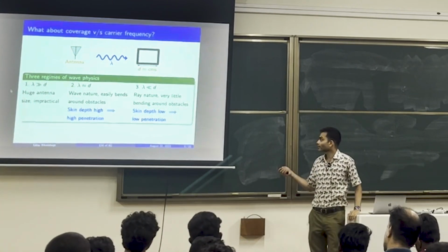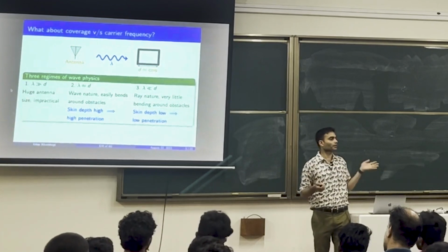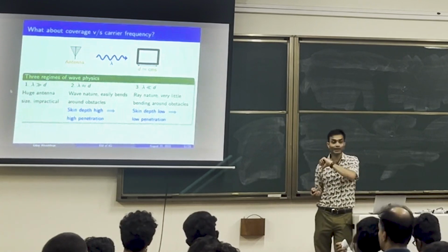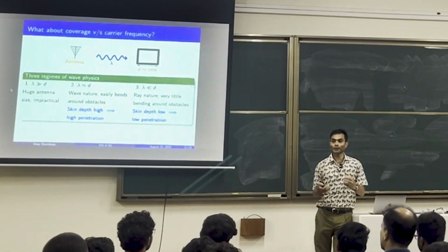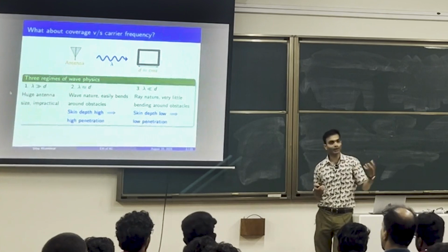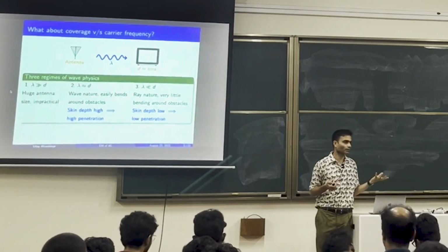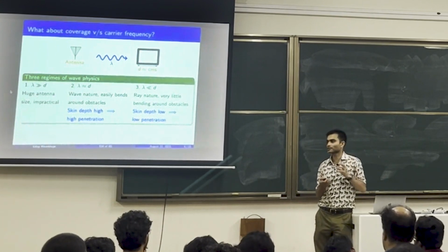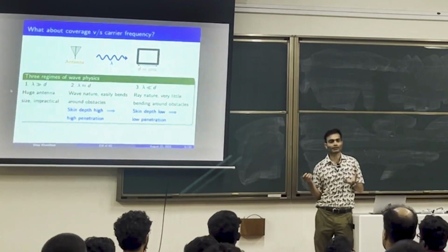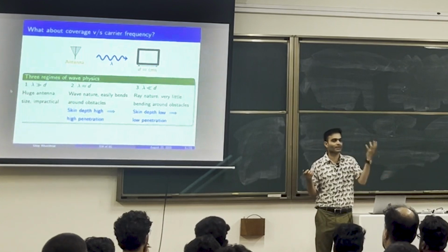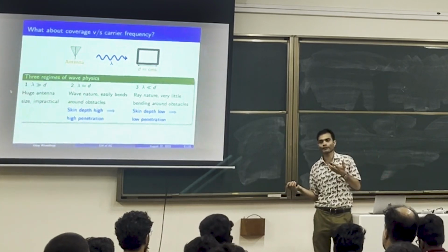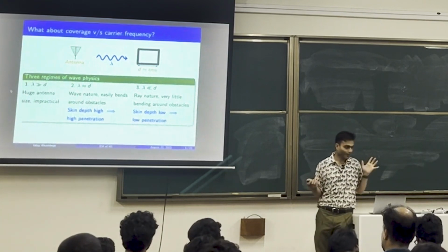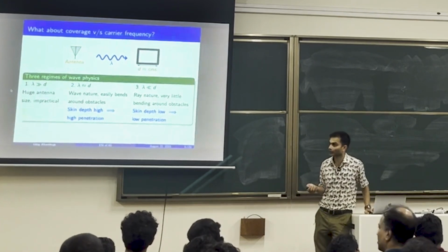So as I go to higher frequencies, what is the takeaway? Coverage is dropping. Attenuation is increasing. That means I need to place more base stations to counter the coverage problem, and I need to put in more power also, right? So this is like we are in the favorite regime of engineering. There's no free lunch. If you win some, you lose some. So by going to higher frequencies, there is more data rate. However, coverage is more and more difficult, right? So this is what we have to work around.